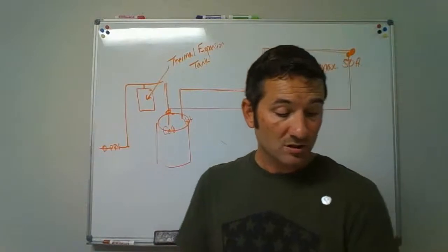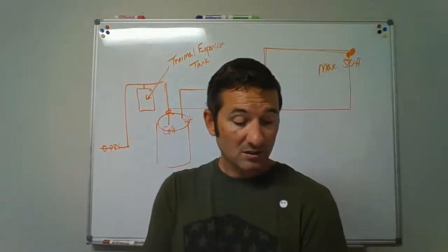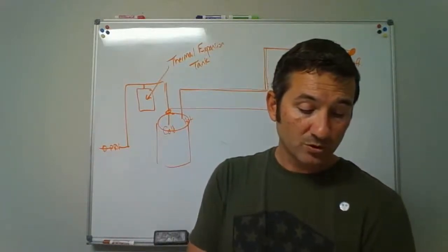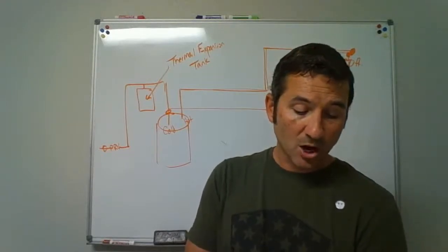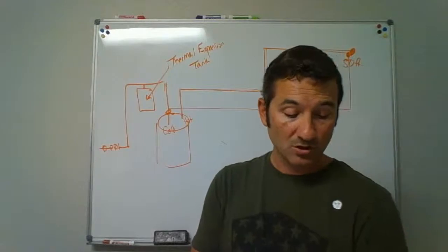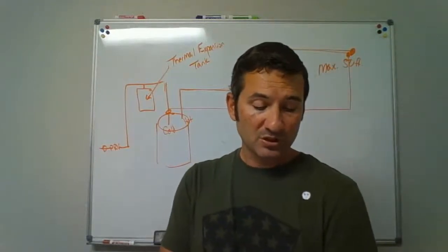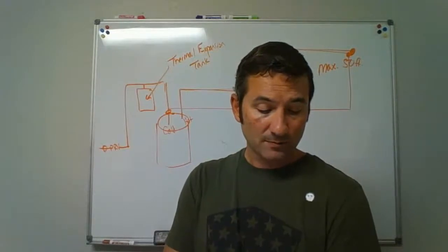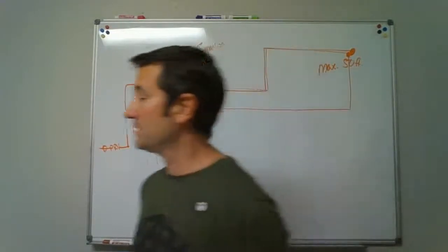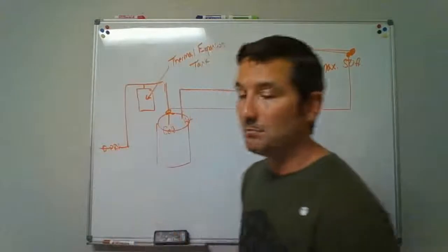Hose connections on page 56, 608.15.4.2. Silcock hose bibs, wall hydrants, other openings with a hose connection, something you could put a hose onto. It's got to be protected by an atmospheric type or pressure type vacuum breaker, okay, or a permanently mounted type of vacuum breaker.